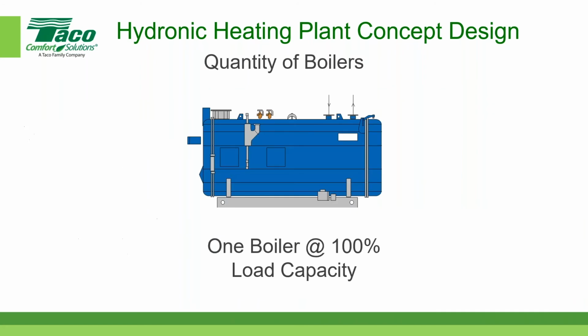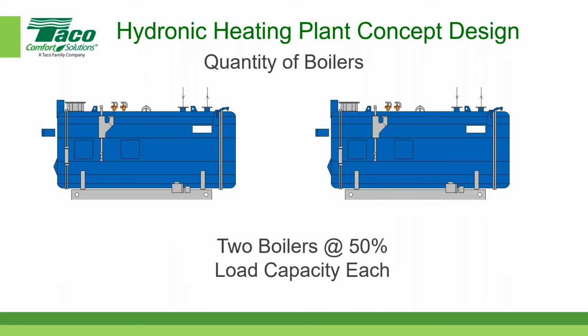Okay. So what about the quantity of boilers? Well, one option is to use one boiler at 100% capacity, or load capacity. Now, one boiler has its pros and cons. One boiler is going to be less expensive than multiple boilers, but if the boiler should fail, you're going to be out of luck in terms of keeping your building heated for the winter. So that's one possibility.